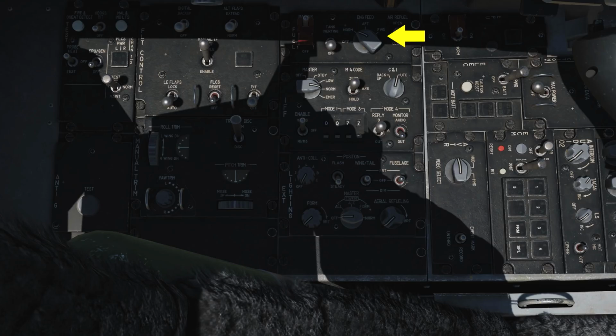An imbalance is most visible on the fuel gauge and is indicated by a divergence between the two fuel needles. The aft and forward settings allow selective pump control for those tanks with crossfeed. These also allow manual shifting of the center of gravity. The normal position allows the fuel system to try to auto balance, and off turns off the fuel pumps.